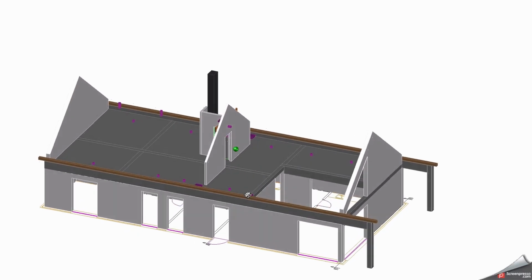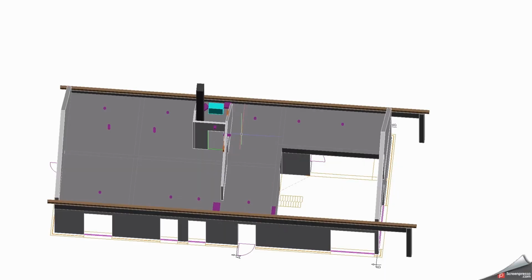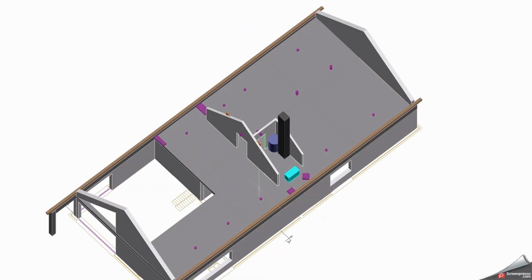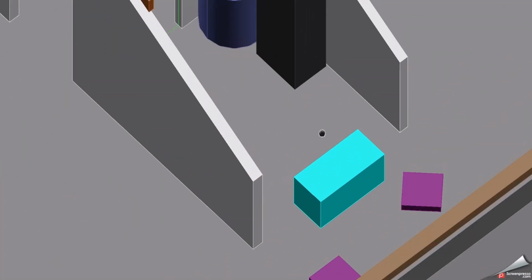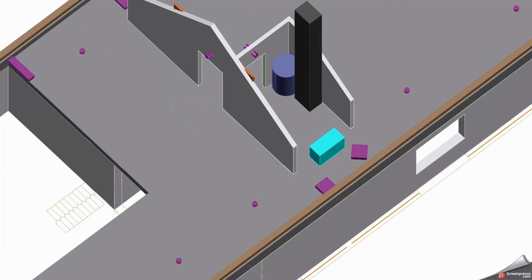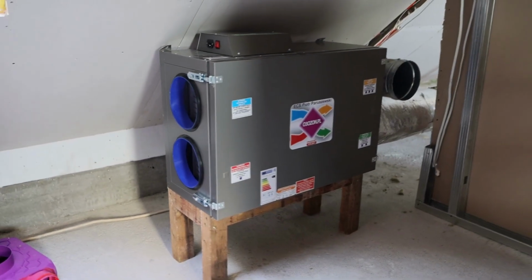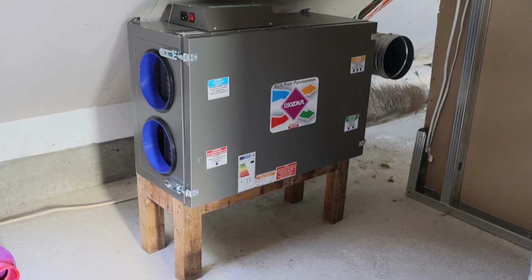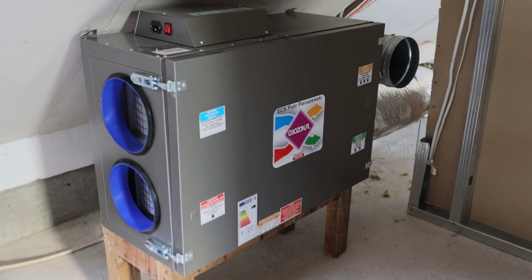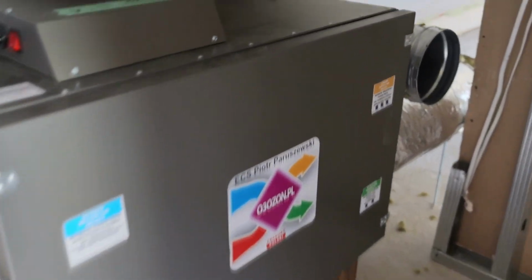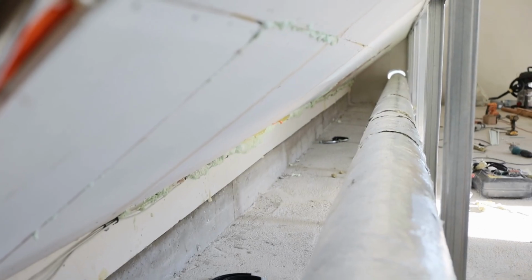The recuperator in the attic will be placed in the technical room, where the boiler's expansion vessel, the chimney, and the attic's electrical panel are also located. In the photograph, you can observe the wooden support structure for the heat recovery ventilator. All the ductwork of our ventilation system has been carefully routed along the knee walls, and these will eventually be hidden from view behind an additional knee wall, which will be constructed using dry lining plasterboard technology.